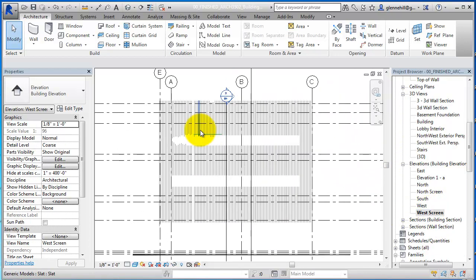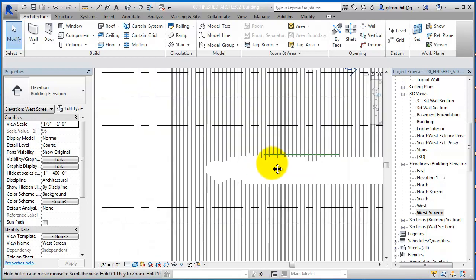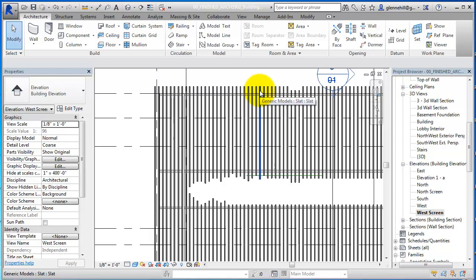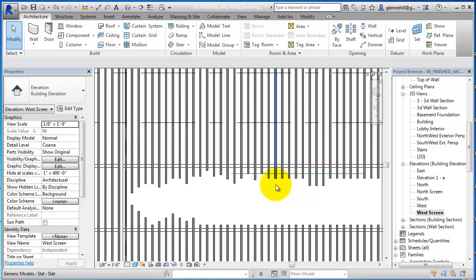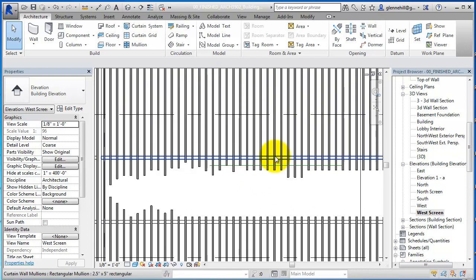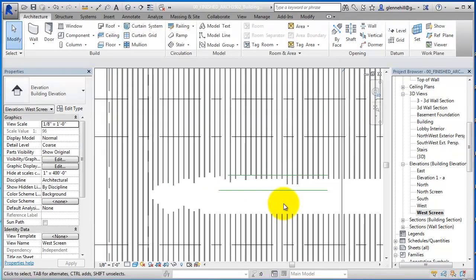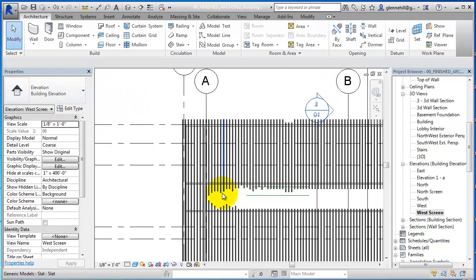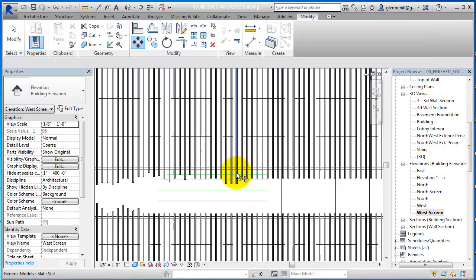screen elevation, and then we can play with the different lengths because I made these as instances. So now we can play with the different lengths. And then of course there's a variety of different ways that I could do that by either moving them. I could set in some model lines as guides, right, for how far I pull them down. So I could draw some model lines, and I can sculpt an interesting opening. Let's move it.